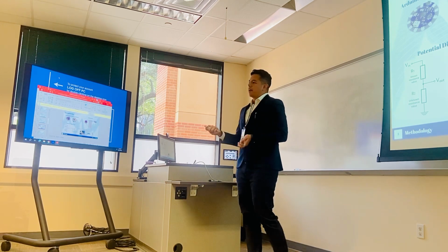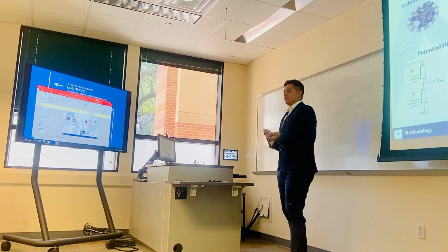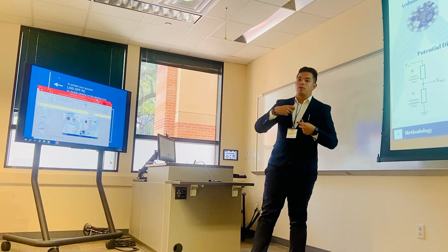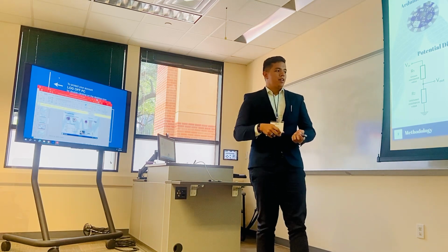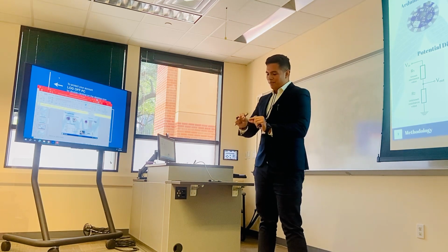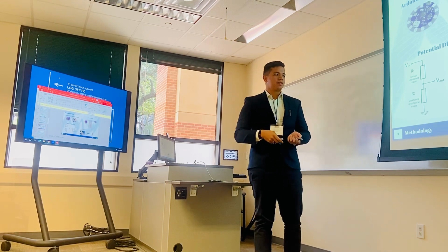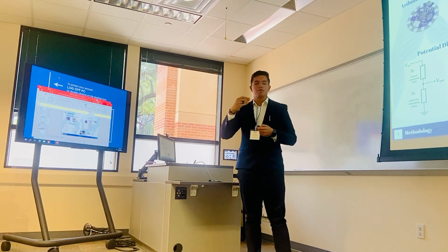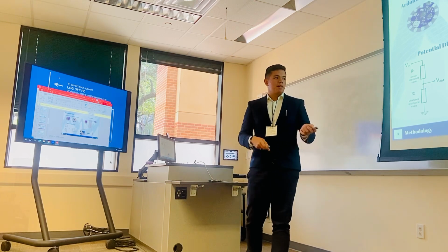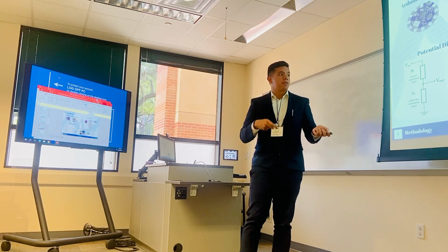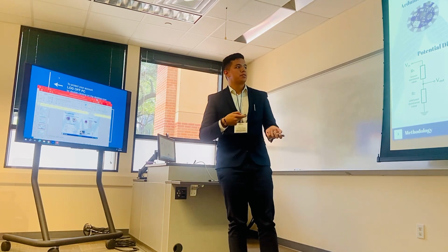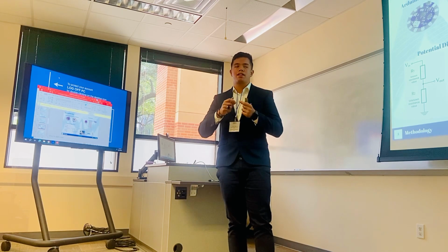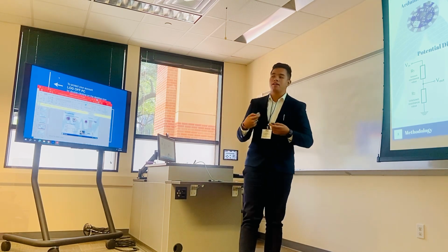So you have to take into account that when you flex the textile fibers, the resistance actually varies quite a lot. So we tried very hard to not move the textile and measure the resistance to get an average value of where the resistance sits. And then we replaced it with a common resistor in a very simple circuit in which we could manipulate the textile and see how the resistance behaved in real time.